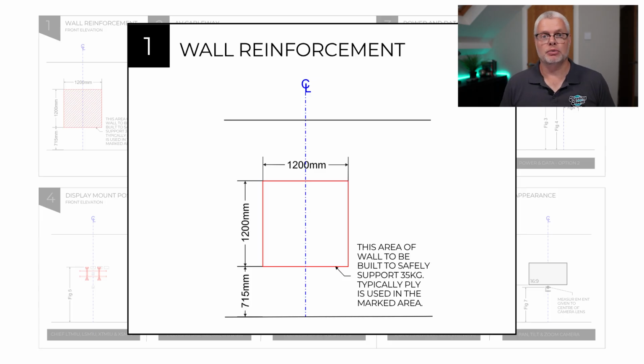A centre line in blue helps orientate the whole installation, providing a fixed reference point to all the trades. Somewhere to measure from, I guess, and it's typically the centre of the room, although it could be referenced against another point, like the centre of a meeting room table.